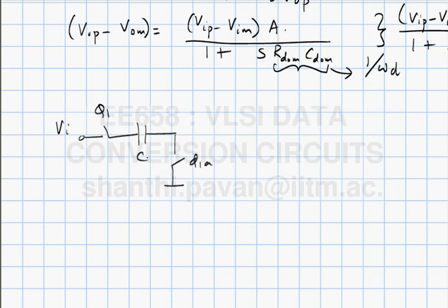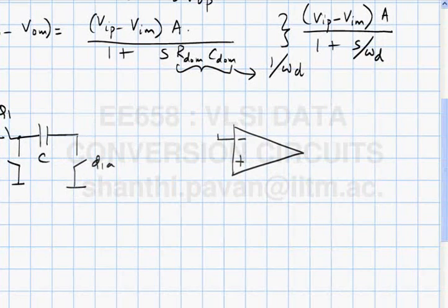So, one way of doing it was to put a voltage controlled voltage source, buffering the capacitor, making sure that charge on the capacitor is safe. Another way of doing it, using switch capacitor techniques, is the following. And the basic idea is that if I had an op amp and if I had a capacitor like this, there was a capacitor charged to a voltage of Vx.